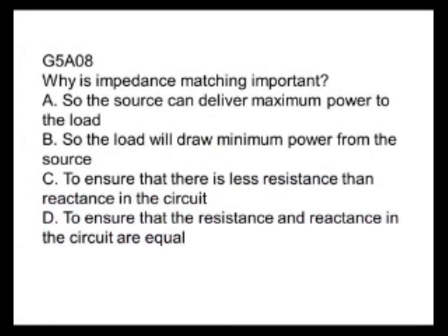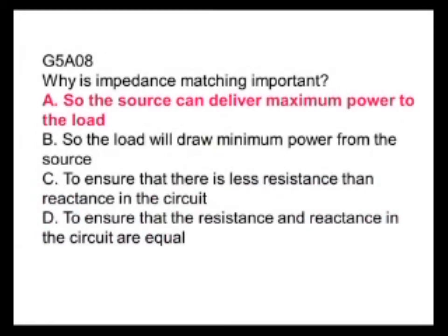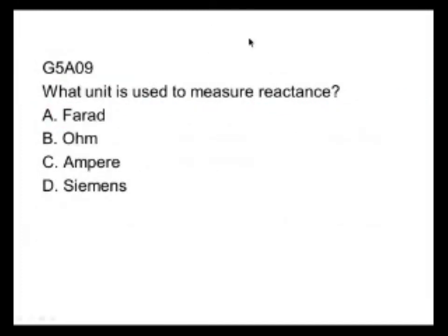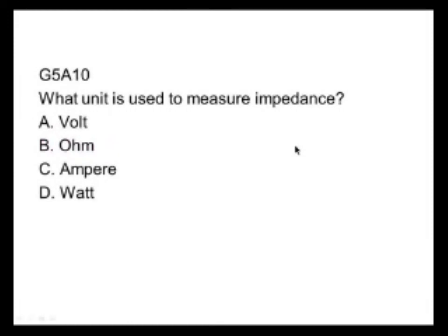Why is impedance matching important? So the source can deliver maximum power to the load. What unit is used to measure reactance? It's the same unit, by name at least, that we use to measure resistance. It's the ohm. What unit is used to measure impedance? Again, it's the ohm.